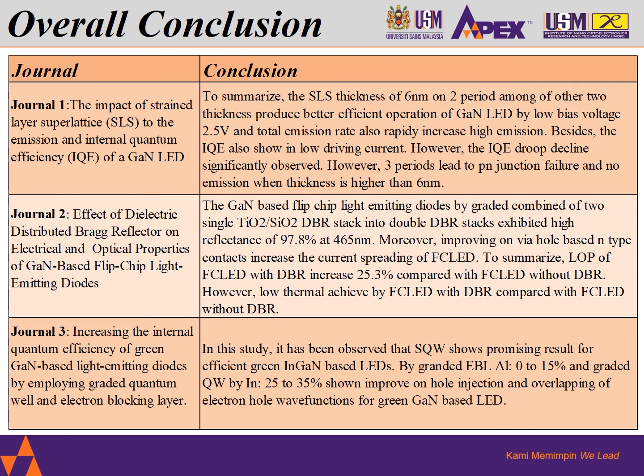The last journal's conclusion is about the EBL. In this study, it has been observed that a single quantum well shows promising results for efficient green indium gallium nitride-based LED. With the EBL, aluminium from 0 to 15%, and the quantum well with indium from 25 to 35%, it shows improvement in hole injection and overlapping of the electron-hole wave function of green GaN-based LED.